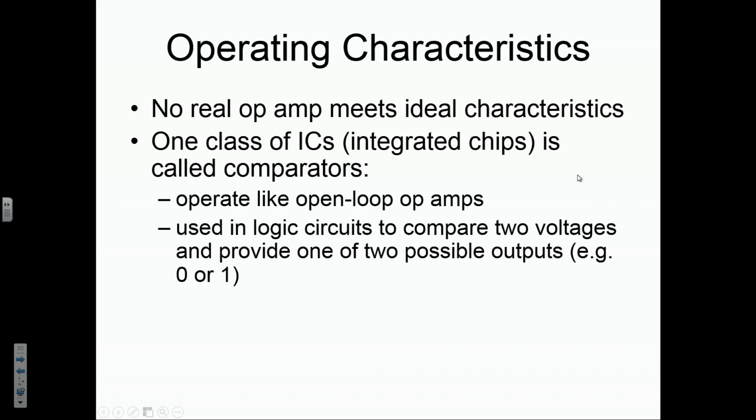If you think about your process diagram, your block diagram, you've got a point where you've got an error detector, if you will, that has a set point and it has an input measurement. And it will compare the input measurement to the set point and give an output to the controller to make a decision on.